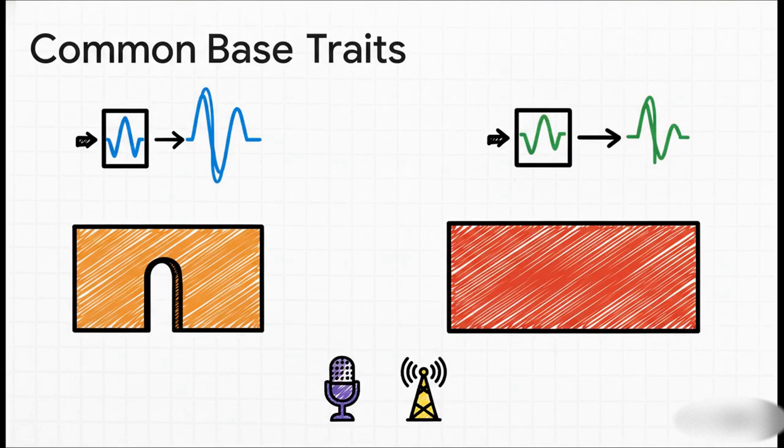So what's its specialty? Well, it's fantastic at boosting the voltage of a signal. I mean, it gives you a big voltage gain, but it doesn't really touch the current. This makes it perfect for things like the very first amplification stage in a microphone preamp, or in radio circuits where you need to amplify a tiny weak voltage signal coming from an antenna.